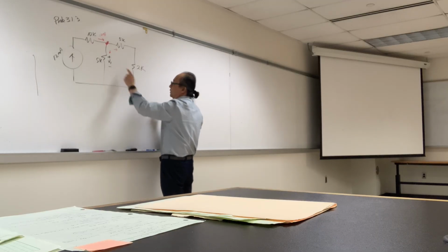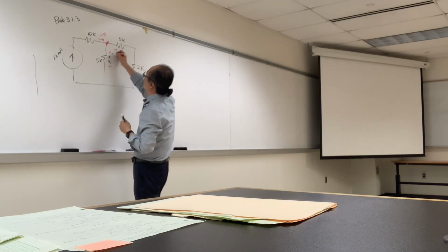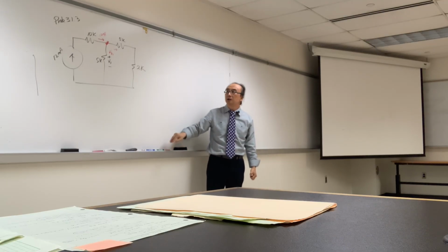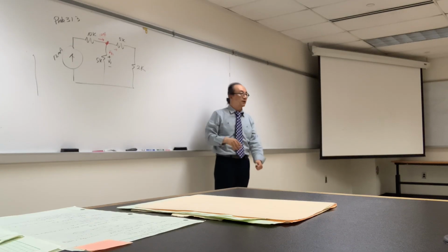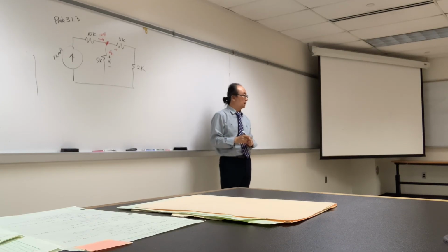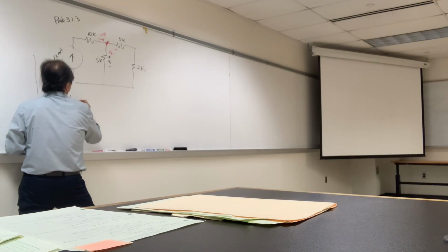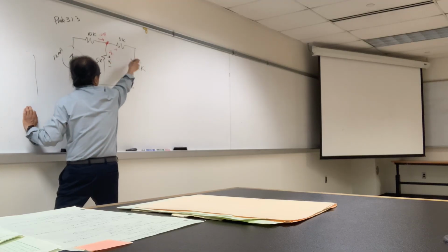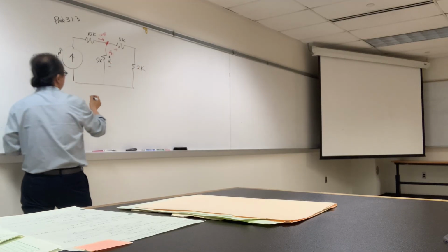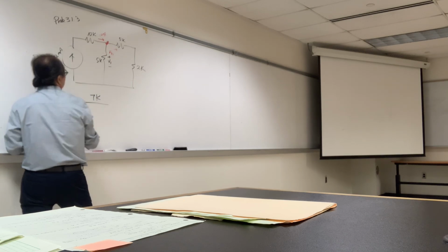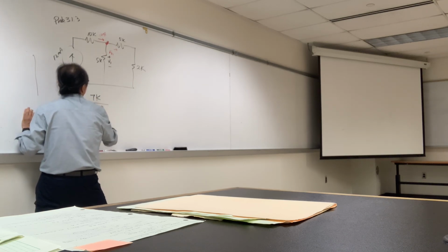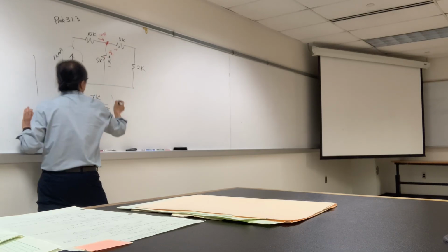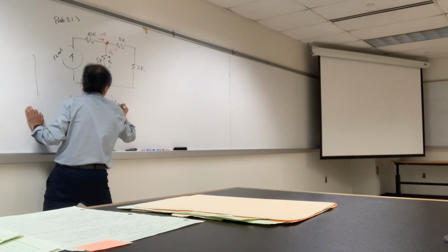So to find the V1, we need to find I sub 1. Once we calculate the I sub 1, V goes to IR. I sub 1 times 5K, that is V1. Simply that's it. So I sub 1 equals opposite, so this 5K is parallel to 5K plus 2K, which is 7K. So 7K opposite at the top, sum of all of those at the denominator, times the total current going in, 12 milliamp.